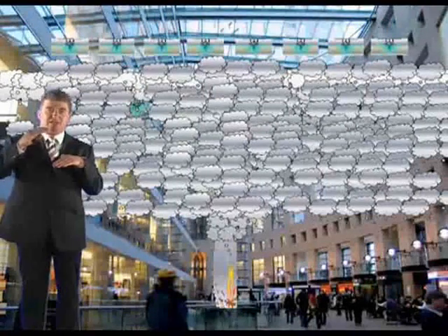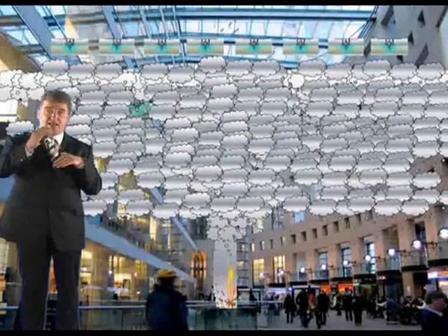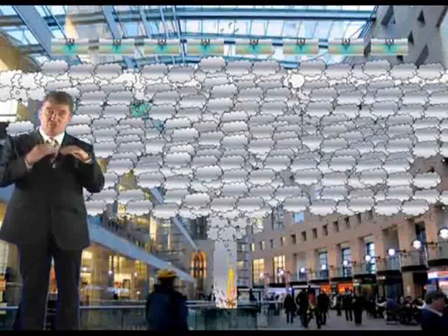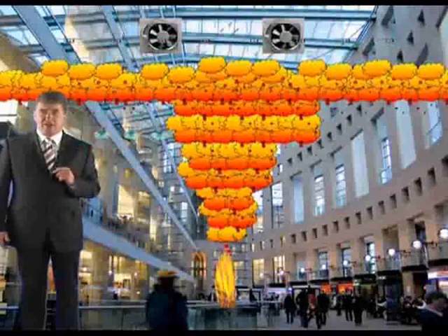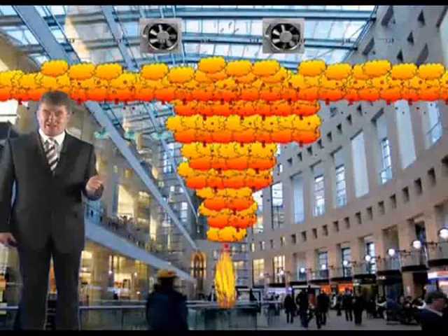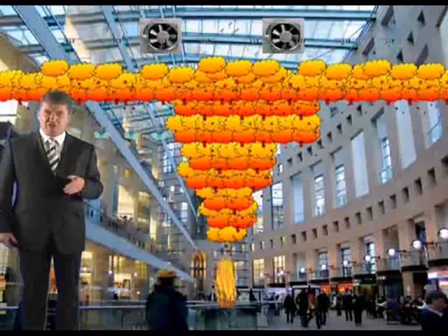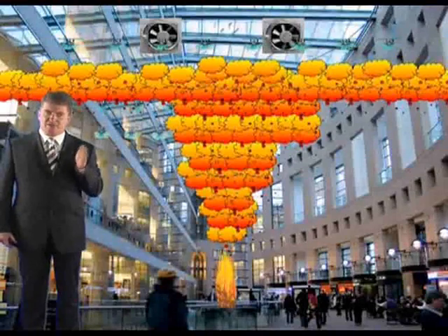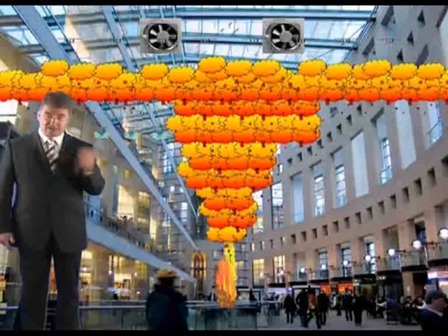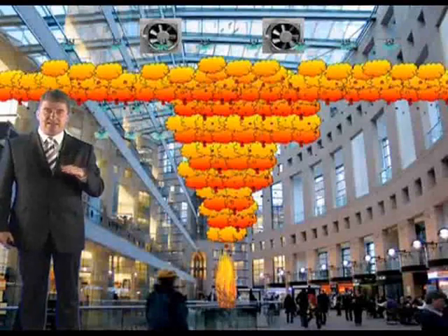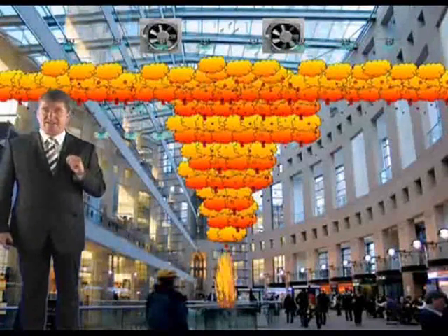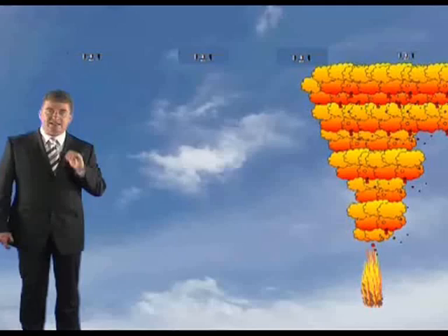So if it's only at 70 degrees and it pops the sprinkler head at 68, well now at 70 it might lose too much buoyancy. That's the first problem. Second problem, conversely, a powered extract system to a reasonable approximation removes a fixed volume of smoke irrespective of its temperature. So that's what it does, it removes certain cubic metres a second. Therefore, if the extent of cooling is overestimated, the system could be under-designed.